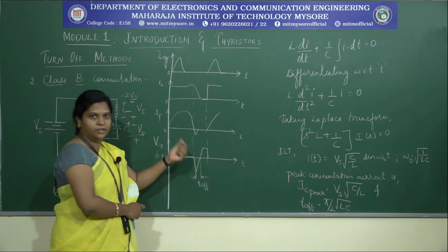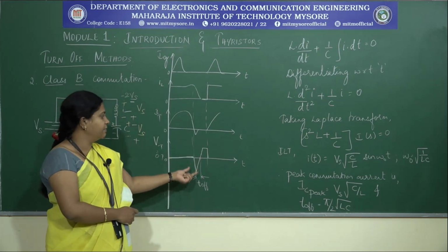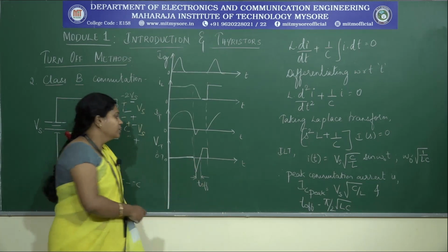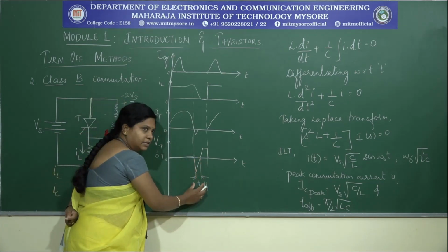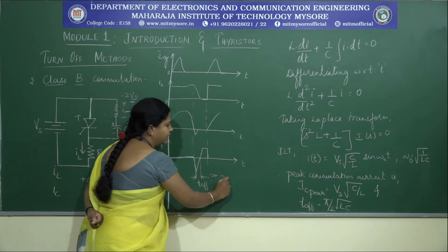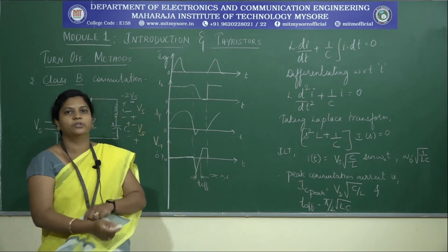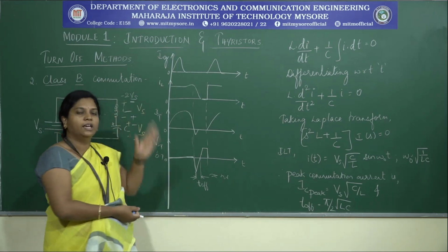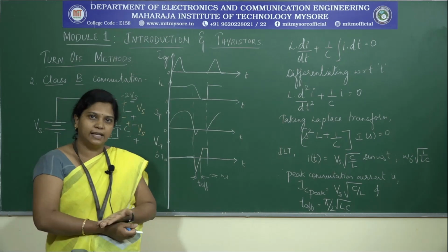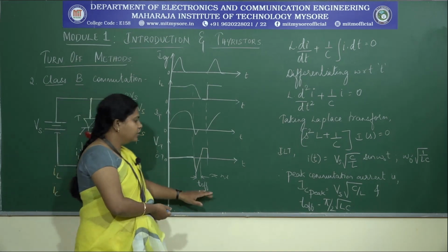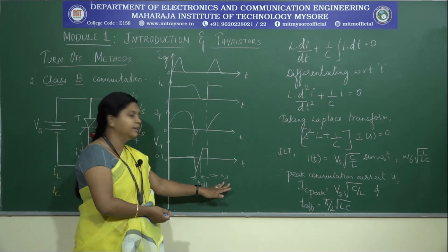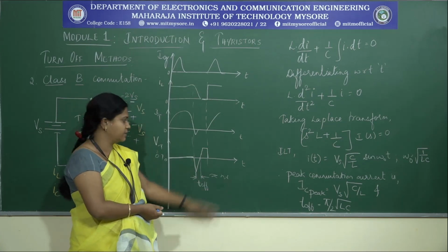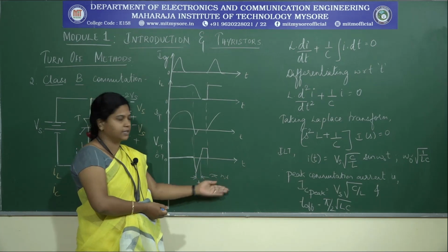During the off state, we know that the reverse recovery time plus the recombination time constitutes the off time. Depending on that time interval, this can be approximately around nanoseconds. If we are using silicon as the material in the PN junction, that is in the thyristor, then the off time will be somewhere in nanoseconds, 10 nanoseconds to 100 nanoseconds or sometimes microseconds.